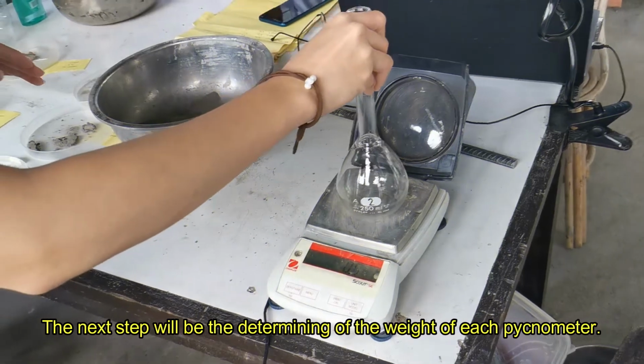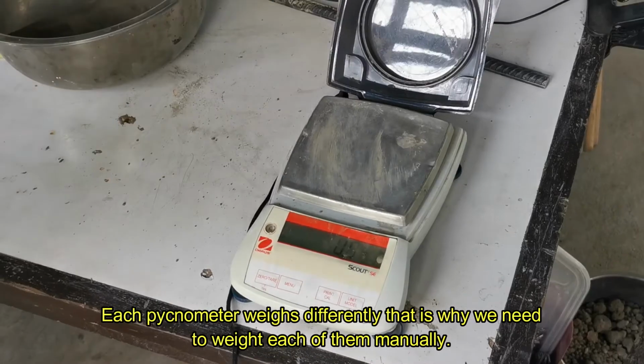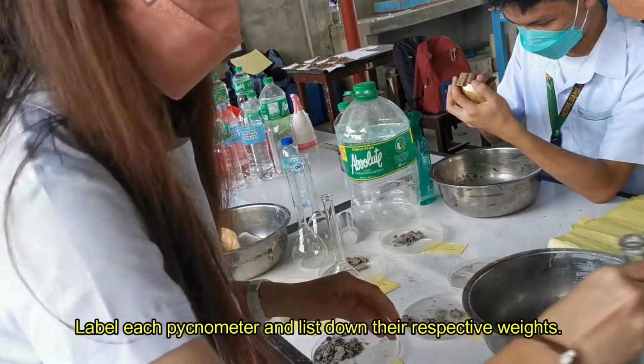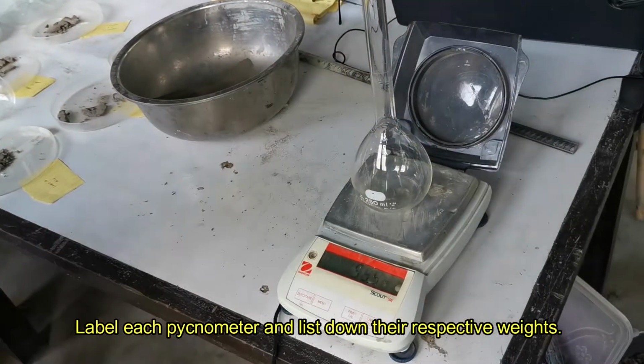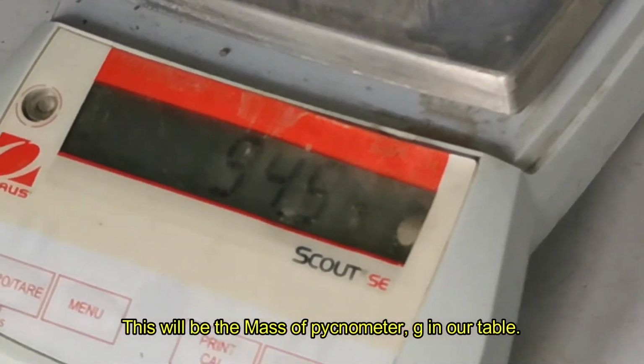The next step will be determining the weight of each pycnometer. Each pycnometer weighs differently, that is why we need to weigh each of them manually. Label each pycnometer and list down the respective weights. This will be the mass of pycnometer, in grams, in our table.